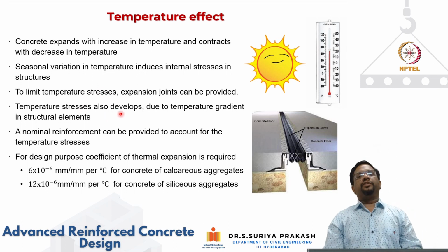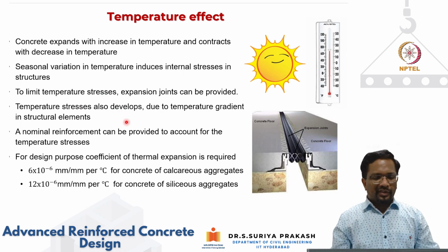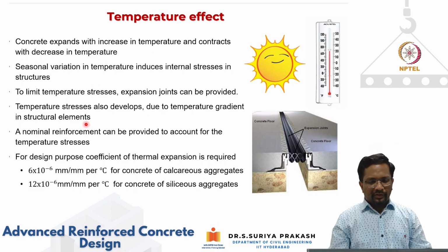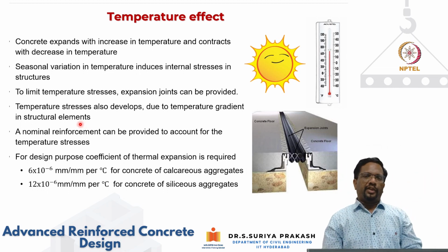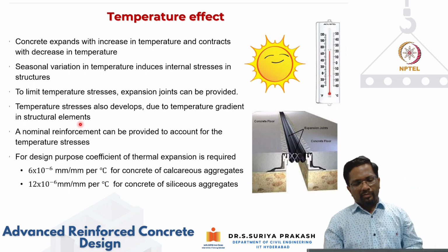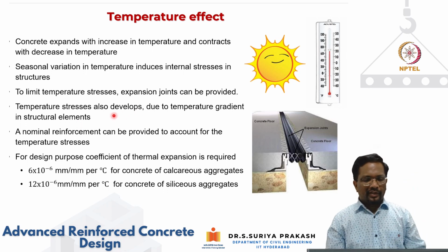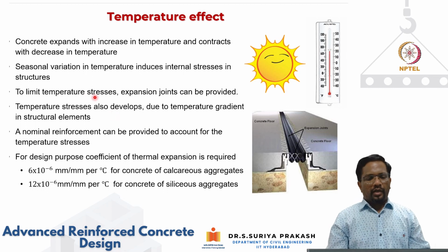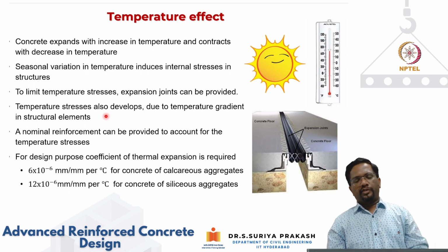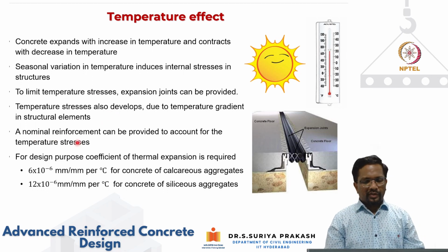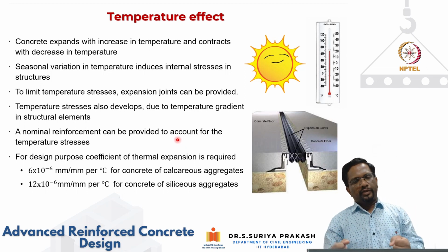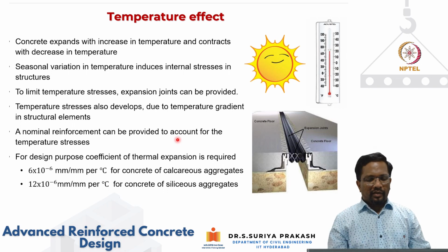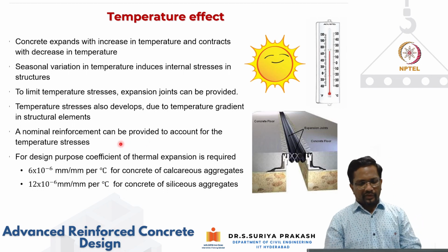And sometimes temperature stresses also develop because of temperature gradient that happens in structural elements. Because one side may be exposed to higher temperature, the other side may be exposed to low temperature. So you will develop some thermal gradient that will also create some thermal stresses. Usually, for accounting for these thermal stresses, what we do is we provide nominal reinforcement that, even after cracking, will limit the crack widths and account for these additional stresses that are developed because of this thermal effect.